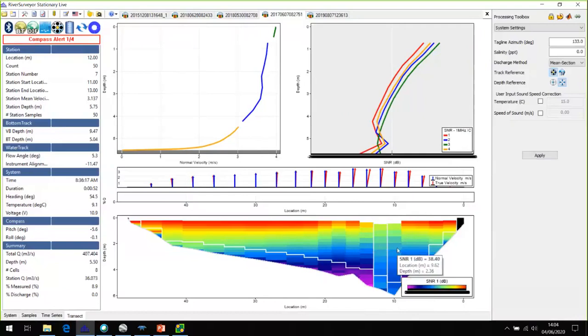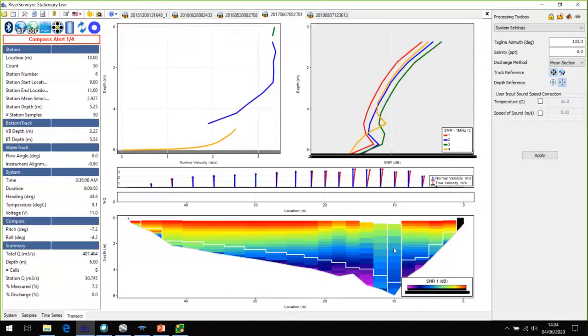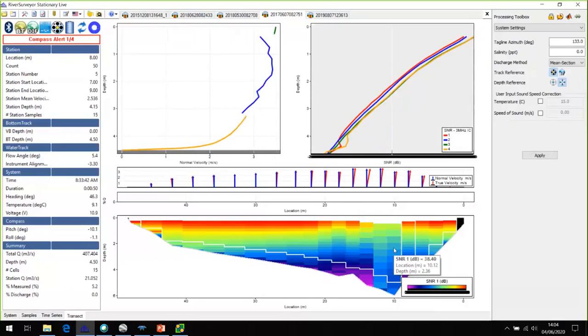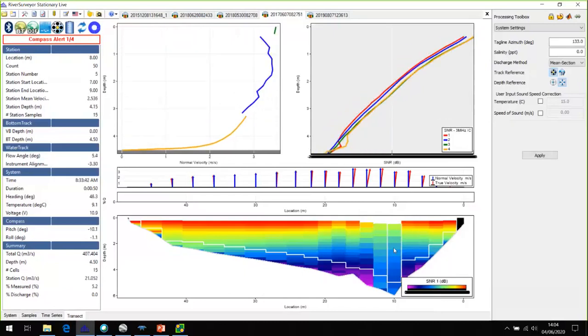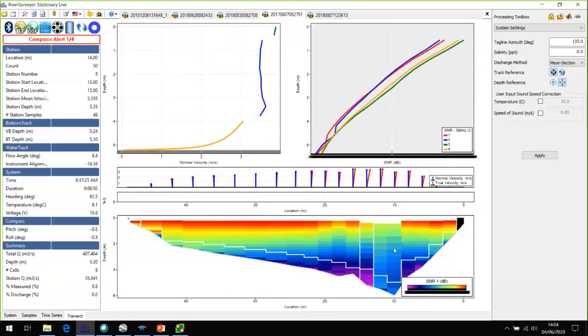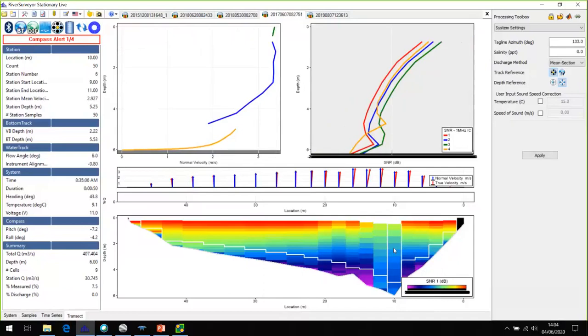That's a real kick up in the data there. So there we go. Horrible SNR, great SNR. But that one now even better. Big strikes off the bed, and then poor again because we're back to 3. So just to show you that it does make a big difference depending on what frequency you're pinging in. Not a problem for your bottom track pings, because as soon as it's 0.8 meters deep, it's in 1 megahertz, but your water track won't change until it's 5 meters deep.